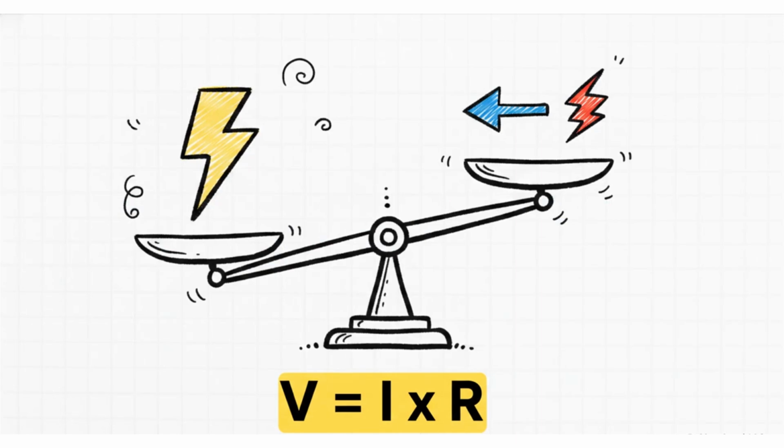And that brings us to the absolute golden rule of electronics, Ohm's law. Voltage equals current multiplied by resistance. This direct mathematical relationship is exactly what makes resistors so perfectly predictable and indispensable in circuit analysis. If you know your voltage and you know the absolute maximum current your component can survive, well, Ohm's law tells you exactly how much resistance you need to drop in to keep the whole system perfectly balanced.